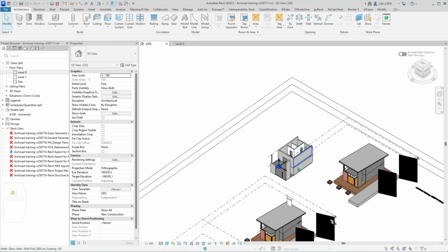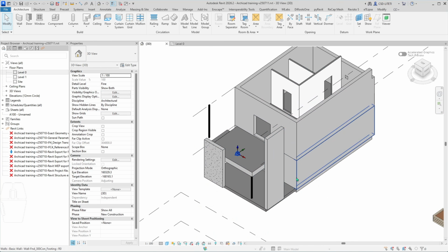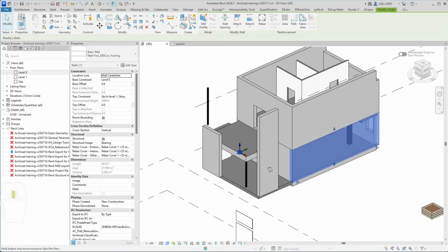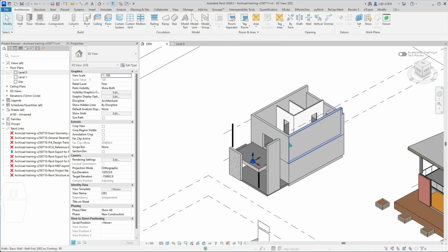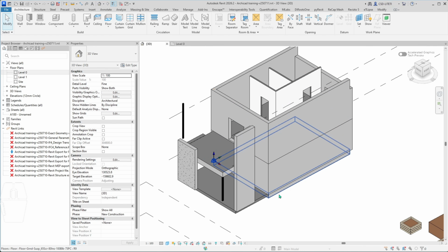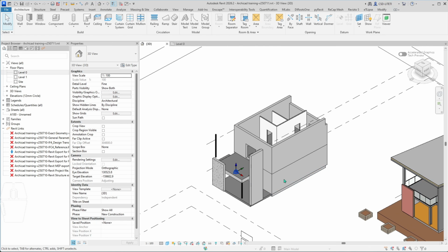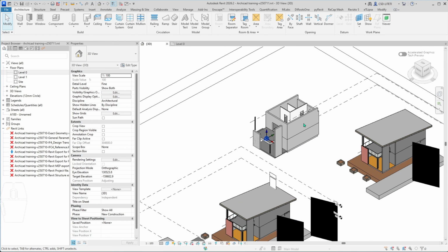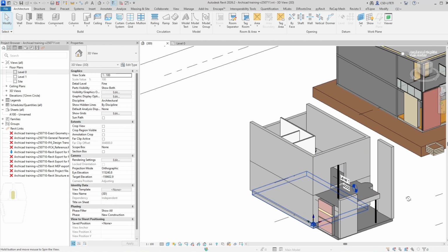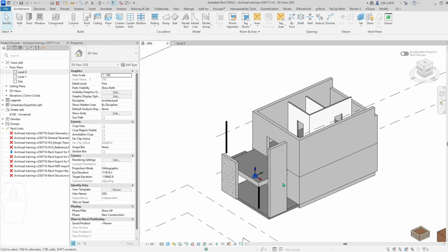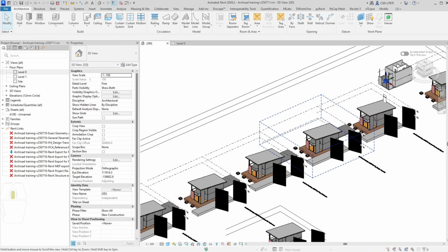And as an additional option, a specific IFC file should be provided for engineers, so they can convert this model to editable Revit shapes, and they can continue working. And by implementing this workflow, engineers can save, I don't know, maybe half of the time for modeling and editing elements.